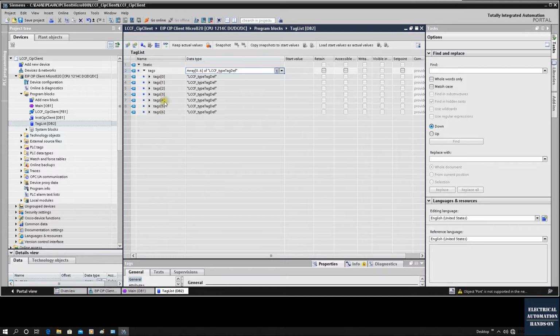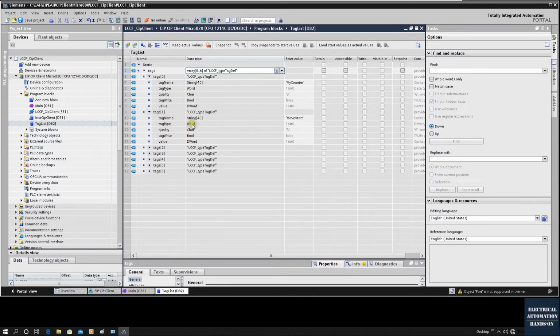That means we open 7 variables of capability for this DB. Once we start up the communication, this controller runs as a client, so it can communicate with 7 variables. When we open each of them, we need to assign the tag name and the tag type.